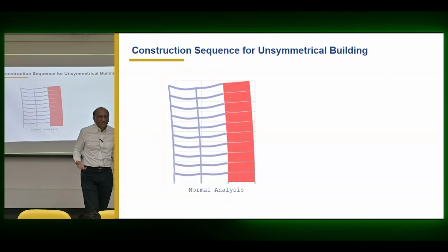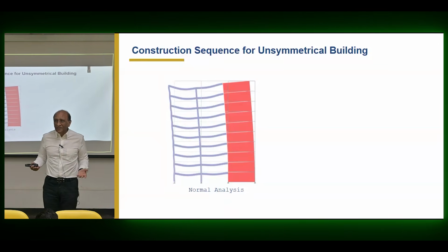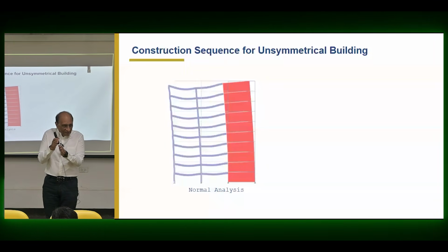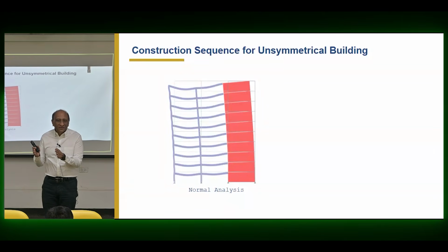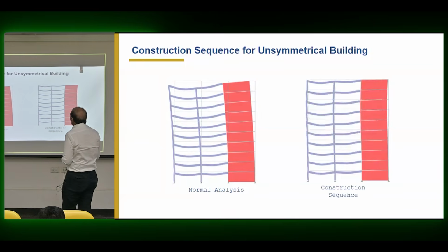The construction people will not let this happen, because the building is not constructed in one day and load applied. It's being built every day. So any deflection happening until that point has already been corrected, which means that corrected shape, corrected direction has to go to the next stage, not the deformed stage. That's what is happening.